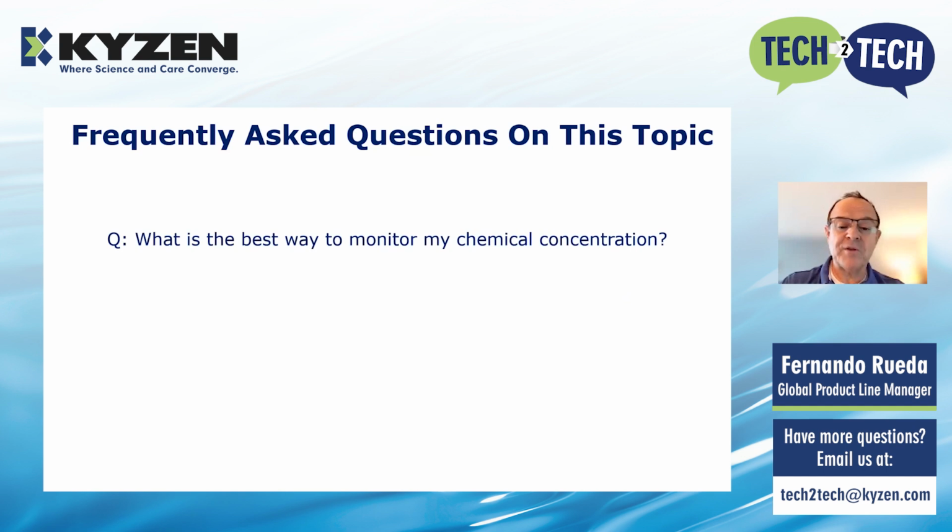What is the best way to monitor my chemical concentration? There are different methods. It's all gonna depend on what you're cleaning and the residues that you're cleaning. Could be titration, conductivity. Some recommend pH. We typically don't. It's not an indicative factor for your bath life, and for your concentration. So we stay away from pH.